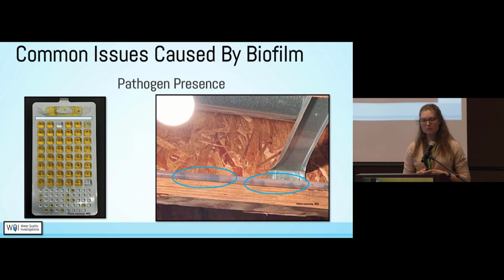One thing I wanted to add that we find extremely helpful is on the left, there's a picture of a Quanti-Tray. Our lab is certified for coliform testing with the IDEXX Colilert method. I'm not trying to endorse a specific product, but what I am trying to say is we don't recommend presence-absence testing. It doesn't really give us much information if you have a positive. We don't know how severe the problem is.